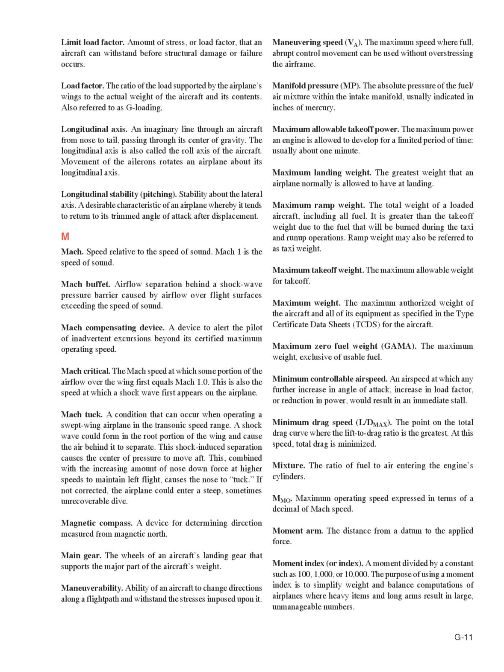Moment arm. The distance from a datum to the applied force. Moment index, or index. A moment divided by a constant such as 100, 1000, or 10,000. The purpose of using a moment index is to simplify weight and balance computations of airplanes where heavy items and long arms result in large, unmanageable numbers.